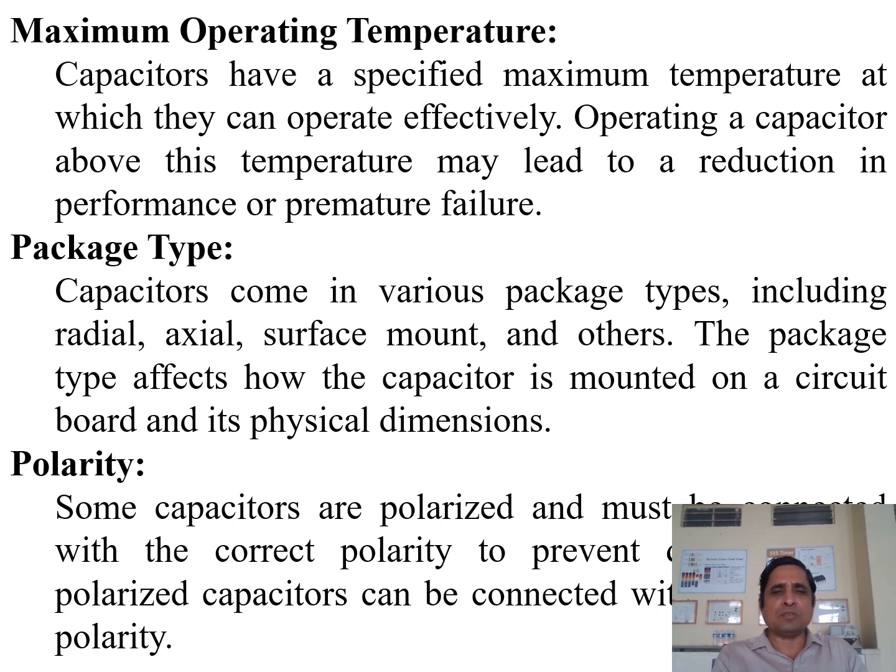Then polarity. So there are two types of capacitors, polarized and non-polarized capacitors. Polarized capacitors have fixed positive and negative terminals. For example, electrolytic capacitor. And some capacitors are non-polarized, meaning they do not have fixed positive and negative terminals. As in a resistor, you can use any terminal as positive and the other terminal as negative. For example, ceramic capacitor.